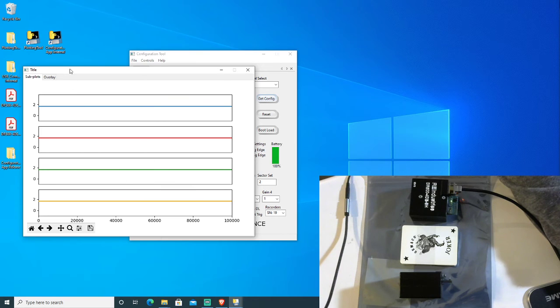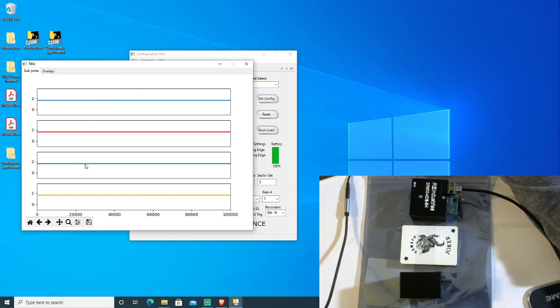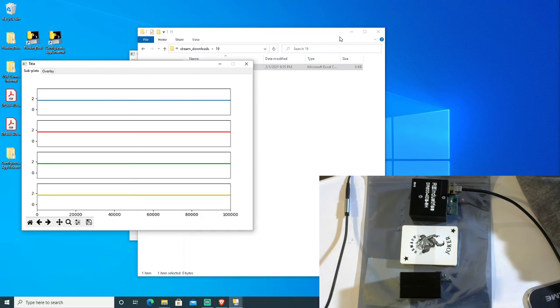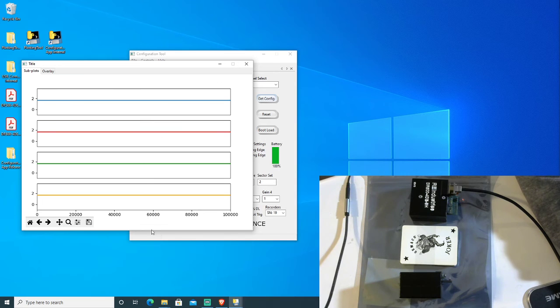So it gives the customer insight into what kind of signals are active on the channels in a low data rate setting. This also logs all the information to a CSV file that's time-stamped and has an incremental number attached to it. This increments every time the heads-up display is open, so all this data is saved and it's streamed into a standard non-proprietary CSV file with a time column and data columns.